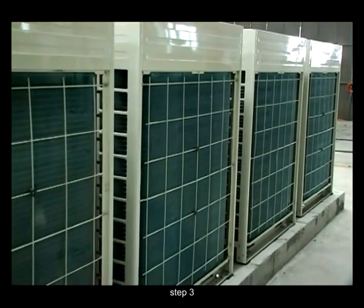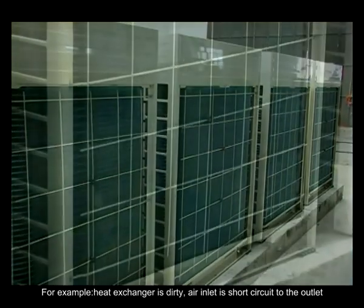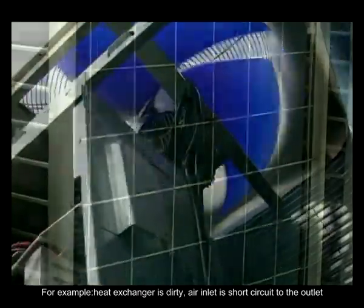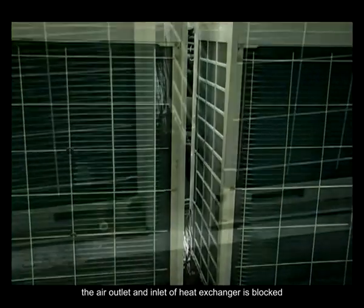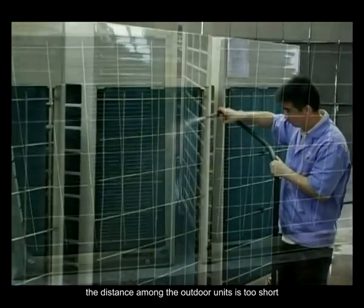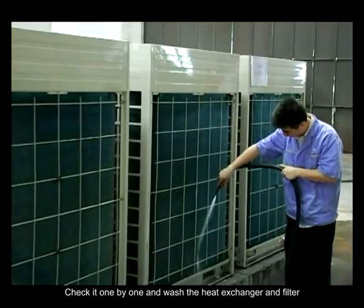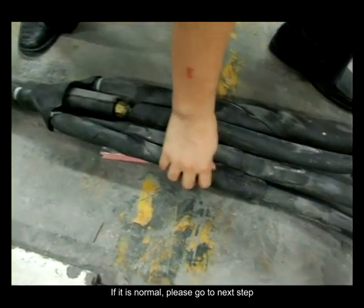Step 3. Check if the outdoor unit is not well heat transfer. For example, heat exchanger is dirty, air inlet is short circuit to the outlet, outdoor fan doesn't work or wind speed is too low, the air outlet and inlet of heat exchanger is blocked, the distance among the outdoor units is too short. Check it one by one and wash the heat exchanger and filter. If it is normal, please go to the next step.